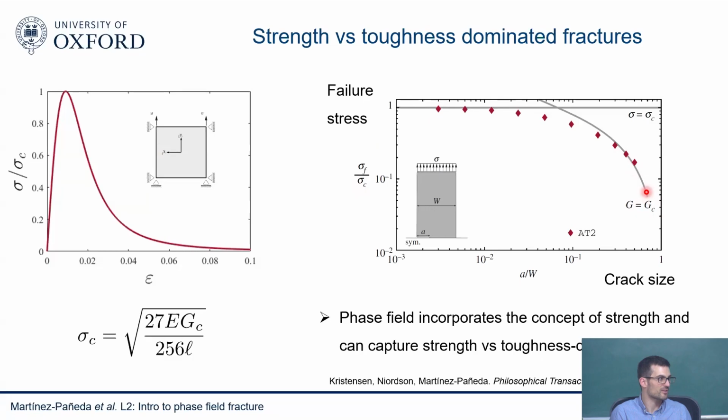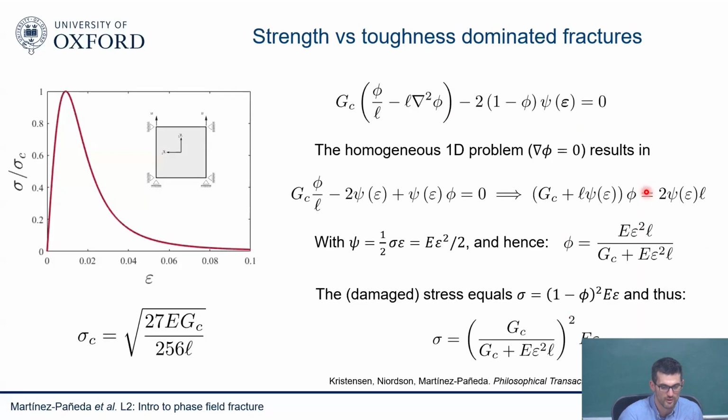The fracture mechanics: how do you calculate G? Is it the GC value, or G? GC is a material property. Yes. So this is embedded into phase field. That's the idea. Whenever you're solving this equation, basically you are at the end. What is G? G is an indication of the fracture driving force. So it's the energy stored in your material. It's basically a regularized version of the strain energy density you could think of. So this is what is happening here. It's all embedded within phase field. I don't need to explicitly calculate G.